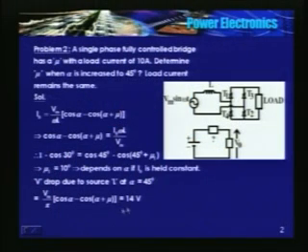Now the voltage drop due to source inductance at alpha equal to 45 degrees, you just substitute here, is found to be 14 volts. It's quite substantial. Again, this is only due to source inductance. Now if I add say 2 volts each, so total voltage drop due to load inductance as well as the voltage drop due to the devices, it comes to around 18 volts.